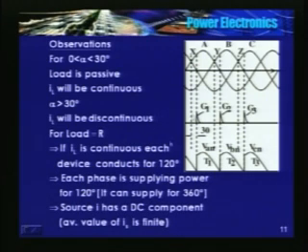Immediately T2 is triggered. At that point the instantaneous value of phase B is sin 60. See, this is 0 for phase B, 30, 60. So instantaneously it will jump to root 3 by 2 per unit, and follows phase B again.